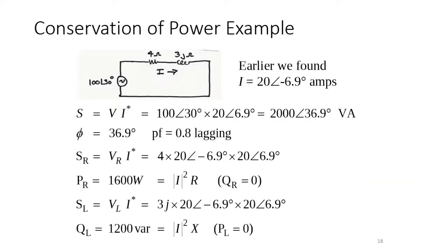Okay, and then we'll just use this. You are already familiar with the circuit in here. If you want to find S in here, first of all, this is ohm and this is ohm. The first thing is to convert all impedances into ohms in the circuit. You cannot add them directly here. This is an imaginary part, a complex number. You cannot add them straightforward. It's not 4 plus 3.